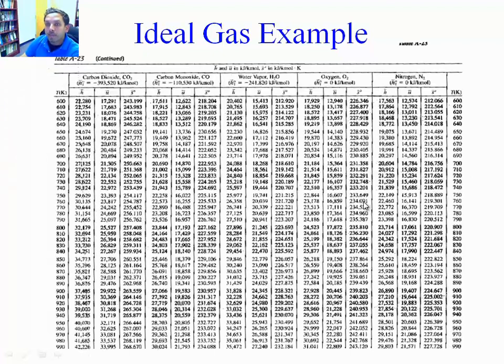And the third temperature, state 3, is 952. Obviously, there's not an entry exactly for 952. There's an entry for 950 and an entry for 960. So somehow we have to interpolate between these values. The value of energy will be somewhere between 32,171 and 32,625. And the value of enthalpy will be somewhere between 40,070 and 40,607. Okay? How do we interpolate?